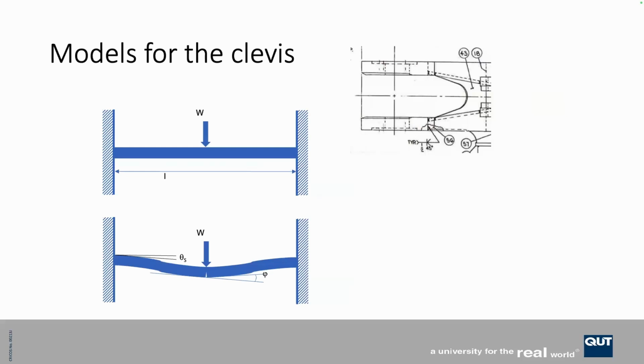The question I was asked was, they said that they did non-destructive testing of this pin by using ultrasonics from one end, and they did it at every 6-month interval. And they said, should this have been picked up at the last 6-month interval? This is a big crack. Instinctively, I would say yes. But could we get some estimate of how fast the crack would grow using fracture mechanics to justify that?